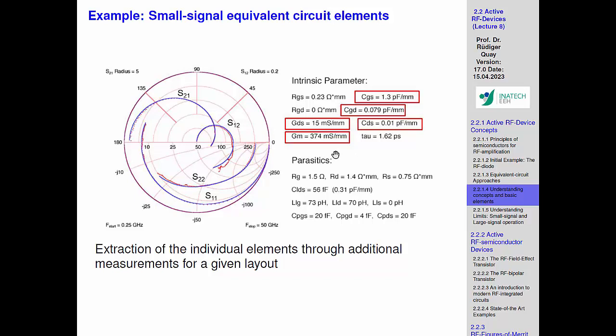And you see there's also significant inductance involved. Yeah, so picohenries, that's just values we have to deal with. That's what a line does. And also the pad capacitances here, you see these are femtofarads, just to give you a flavor that a piece of metal, when you put it on the substrate, you get even additional contributions.